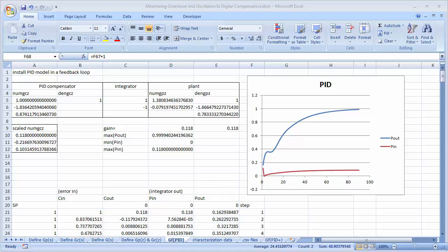Now let's go through the steps of system identification, plant modeling, and building a compensator. In real systems, the plant may be difficult to model. The approach is to put the physical plant in a very simple closed loop with a single coefficient compensator and an integrator to remove steady-state error. This is all done in system using the actual processor, electronics, and other components that would make up the final embodiment of the complete system. We choose the single proportional gain coefficient to be very small, say 1 or 2% of the error input, so that the loop regulates with a little overshoot and oscillation.